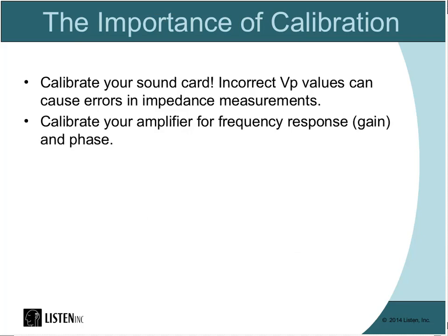It's also very important to calibrate your amplifier for frequency response and phase. I will show you later how that automatically gets taken out of the final impedance measurement, so to a certain degree, it shouldn't matter what the frequency response of your amplifier is.